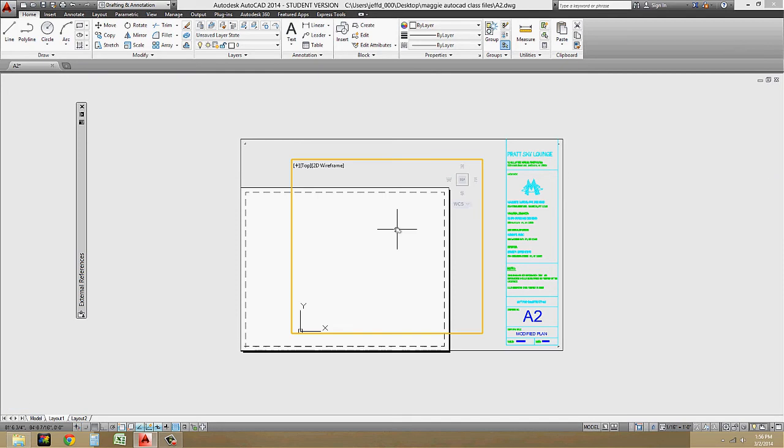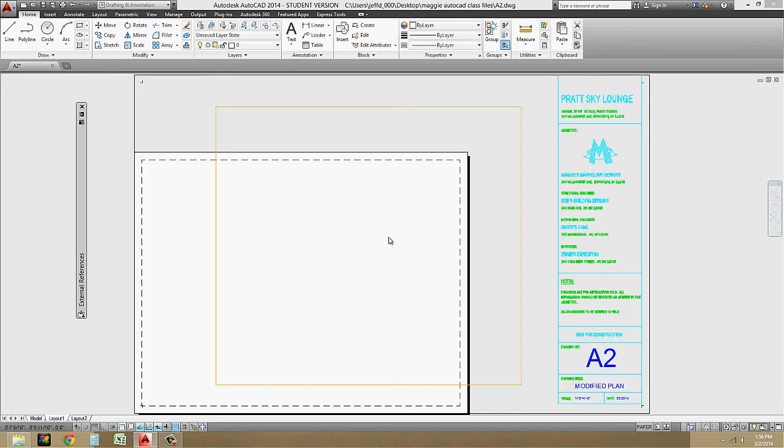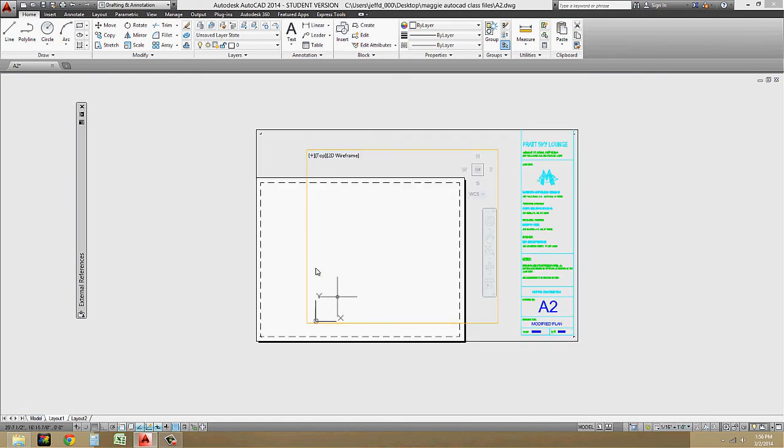Okay, so if I double click inside of that and I do a zoom extents, so I'm zooming to the extents of the, oops, sorry, let's unlock that. Now zoom extents, and zoom to the extents of the viewport, okay, nothing shows up. And I can try to scale in, scale out, and try to see where my XREF is. But a lot of times, and typically, when you do detach the XREF and attach it again, it doesn't, for some reason, show up again in the viewport. And that's fine. All I have to do is select this and get rid of it, so I erased it.